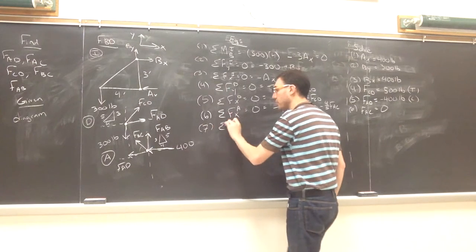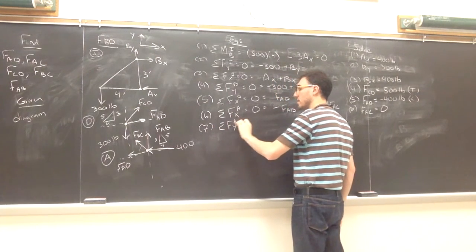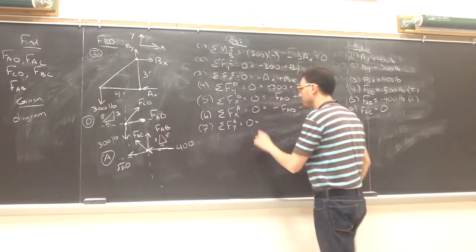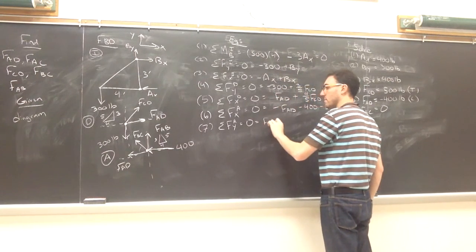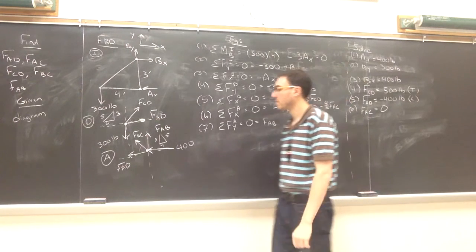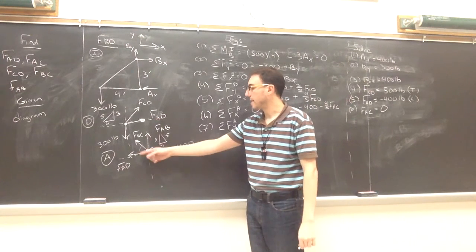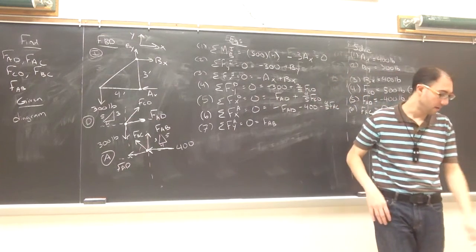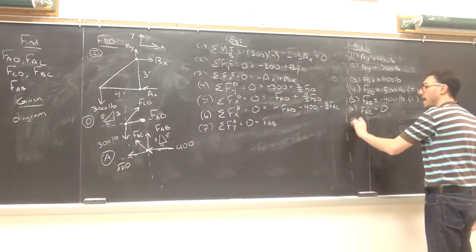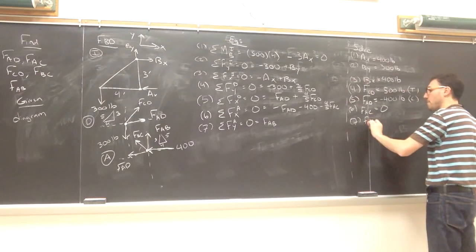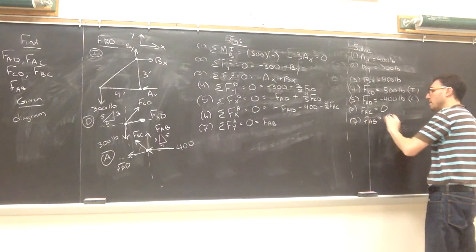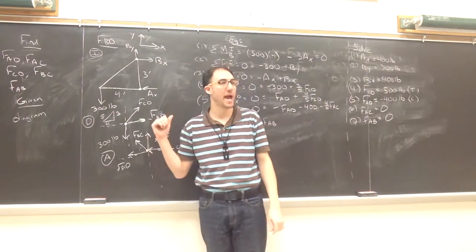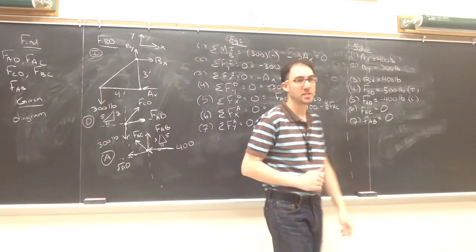That was the x direction. And now in the y direction, that will be FAB, that's in the x, plus a component of FAC. But I already know FAC is 0. So actually it turns out that FAB is a zero force member. We couldn't identify that, though, based on our rules, but mathematically, that did turn out to be the case.